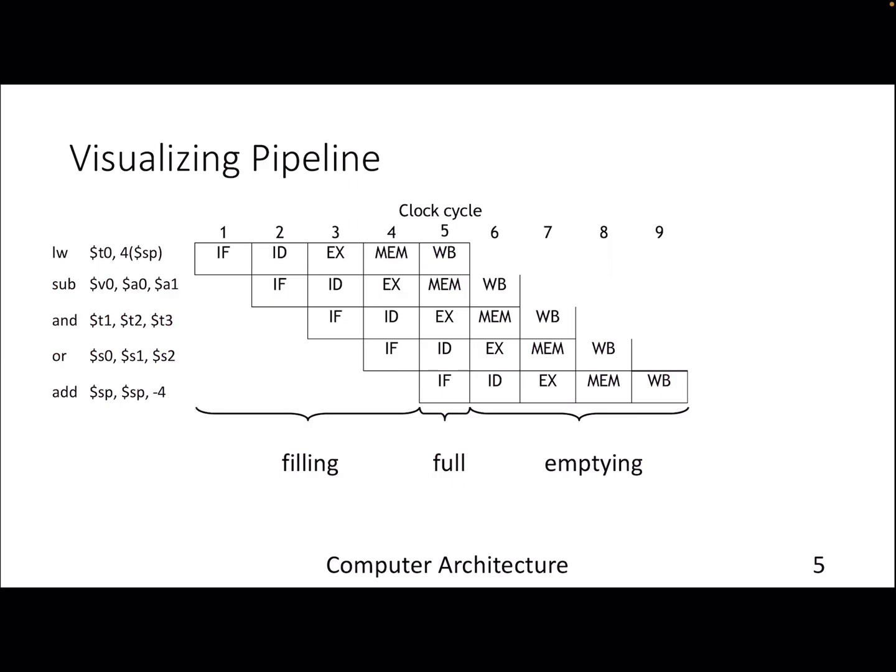You can also look at it this way, where you populate all the instructions that are going through the pipeline in this order. So this is the sequence of instructions. And this is the time window. And whatever I have discussed in the previous slide, the same applies here. So you move from left to right. First cycle, first instruction is in the fetch. Second cycle, first instruction is in decode. Second instruction is in the fetch stage, right? And like that, it goes on.